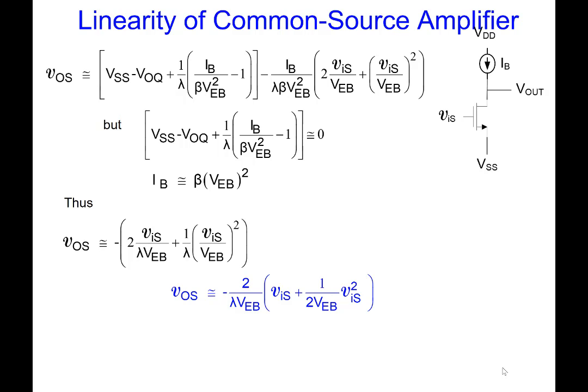So if you want to get low distortion, you want to make the excess bias what? Usually we want low distortion for building amplifier. So as a designer, what do you have to do to get low distortion? Make V excess bias high.